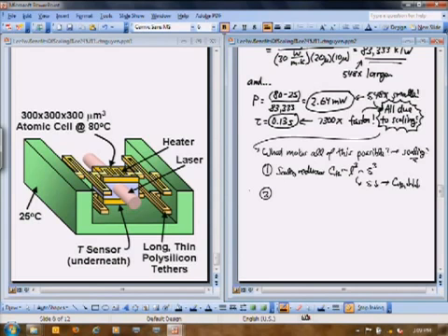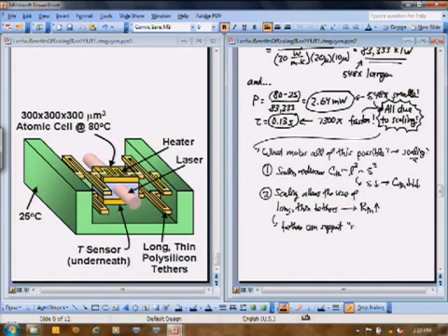And these long, thin tethers then means that thermal resistance goes up. Because remember, resistance, whether it's thermal or electrical, goes up as the length of that material gets longer. Okay? And so what does this mean in the mechanical case? Basically, tethers can support more, which I'll put in quotes, when things are scaled. You can almost say they're getting stronger. Okay? So why is that?